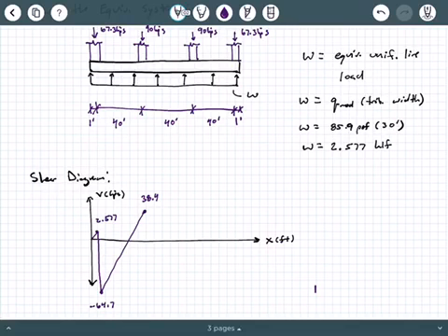And then, of course, we encounter the 90 kips pointing down, so we say minus 90, and that's going to jump us back down to a value equal to about negative 51.6, okay? And then what do we encounter next? Well, we encounter the next 40-foot spread of 2.577 KLF. So we're at negative 51.6, so we're going to say plus 2.577 times 40 feet. And guess what? That's going to linearly increase us up to a value of about 51.4.